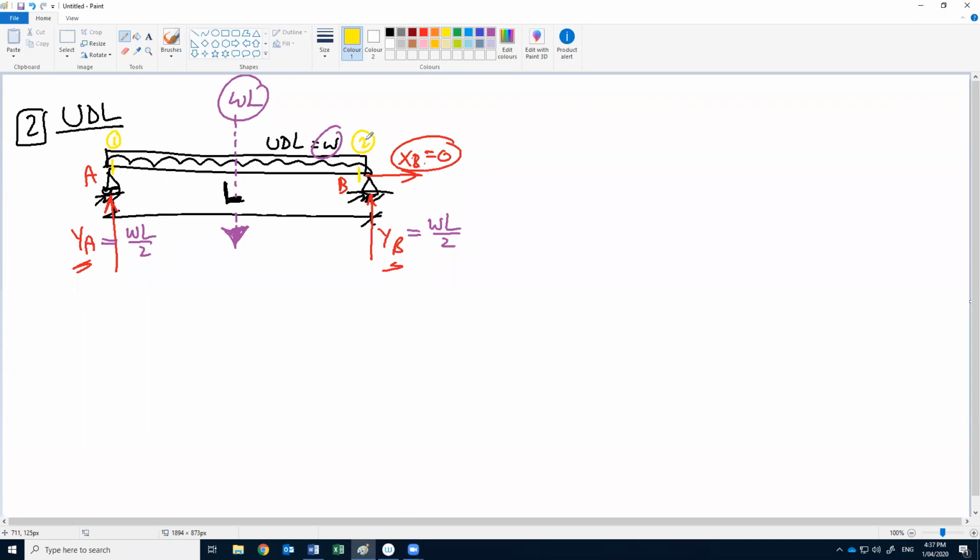Okay. Do we need more? We said one at the beginning and one at the end, and one before and after a concentrated load. Do we have any concentrated load here? No. So we don't need to. This is not a concentrated load, right? No, this is only the equivalent force for the uniform load. So we have only 2 cuts, one at the start and one at the end of the uniform load. So we will have one here and one here.